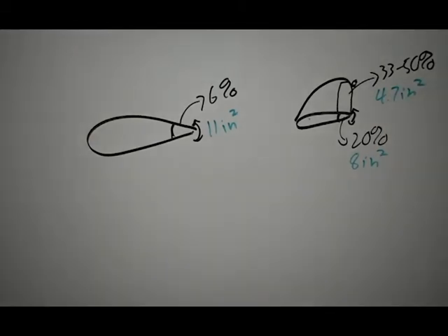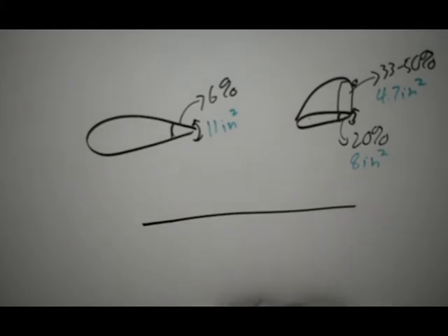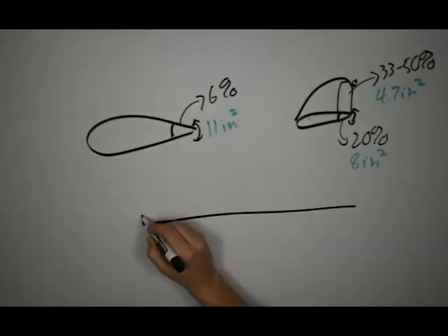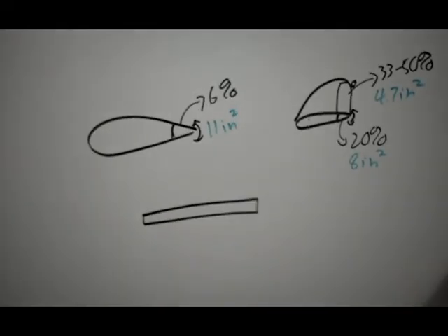When you're choosing the dimensions for your control surfaces, you want to try and make them something that you can actually build. You don't want a really long aileron that's only 1/8 inch wide, because that's going to be really difficult to build and support on your aircraft. Instead, you might want to go with something that's way shorter, but about 1/2 inch wide.